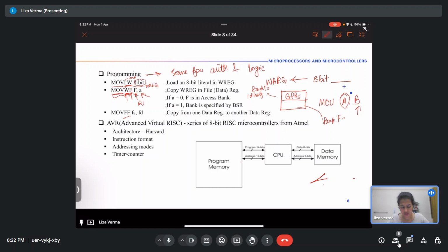I think they were explained fairly in class. So in register direct, you give just the instruction and one of the registers. Let's say increment R1 or R2, clear your R, or any kind of arithmetic or logic instruction. Let's say you have XOR R, so it will XOR R0 with R0 itself. Okay. Then you have register direct with two registers, similar to this add instruction.